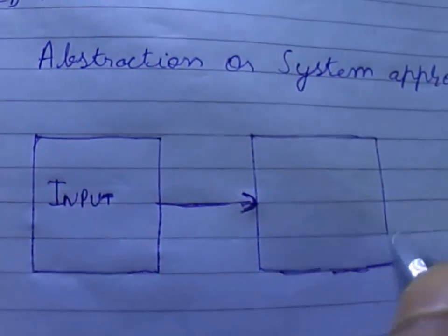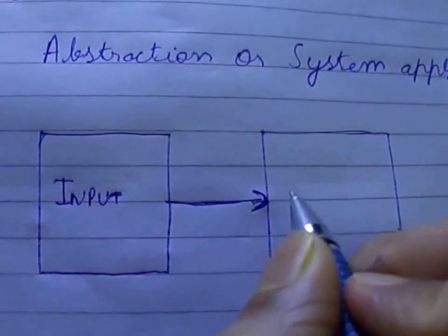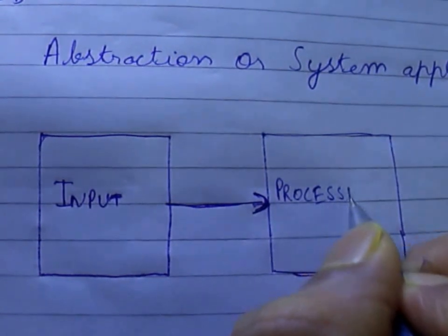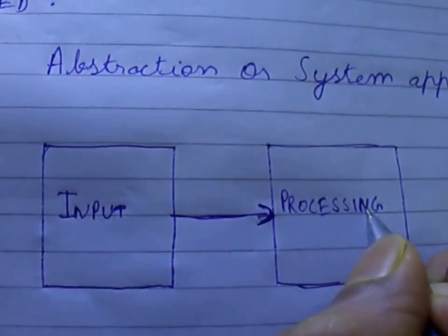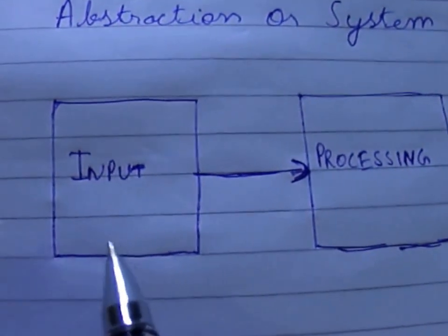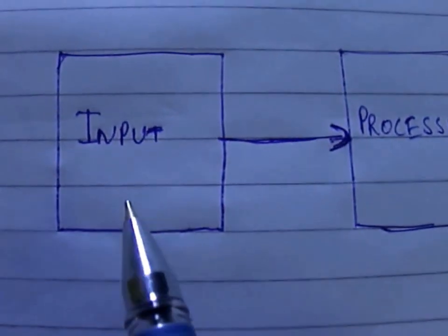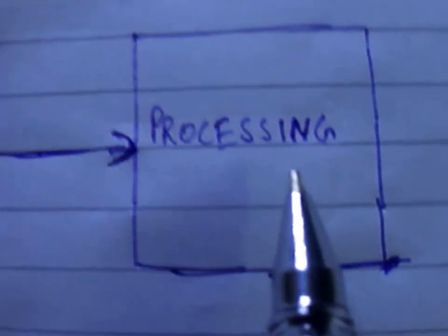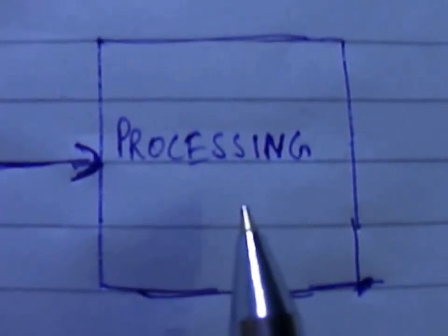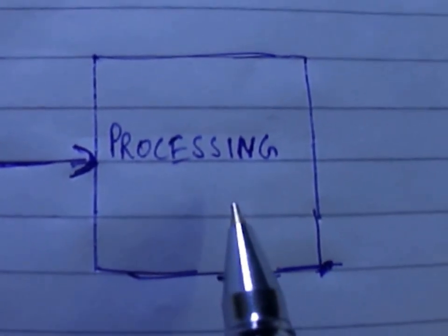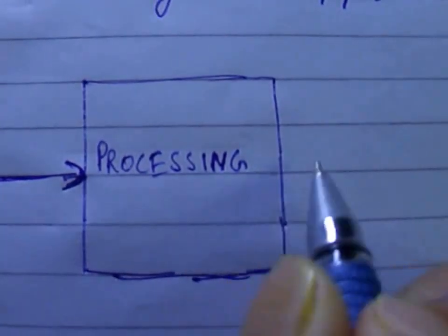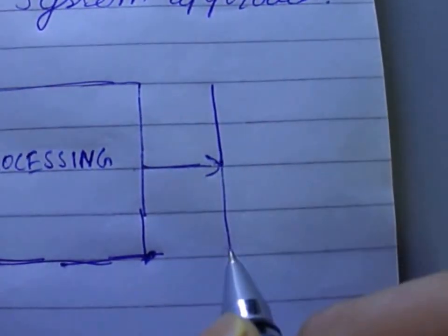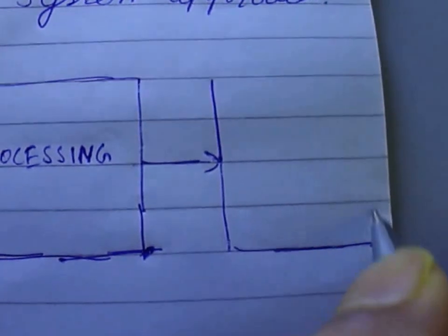which I like to call the processing part, or the process. This is the processing. We will get the input from the input modules like the sensor. In this case, LDR is the sensor, and then it will be processed by an IC, and in this case it will be the 4510 BCD counter, and that processed information will be shown in the form of output, because processed information is in a form which is